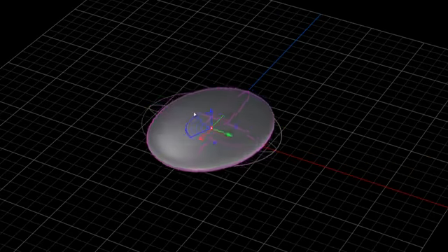All right, there are some also important keyboard shortcuts to know as we're using the Rhino 5 gumball. The first one is we showed you how I can scale with that particular handle. Okay, so that's just a 1D scale. If I click on this and hold down Shift, this will allow me to do a full 3D scale.